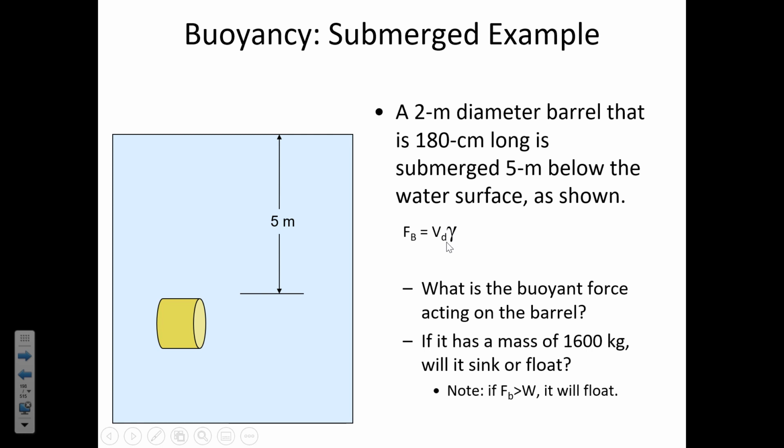You know, liquids are only minusculely compressible. And you'll only notice a difference in the unit weight of the liquid when you go thousands and thousands of meters down. That's when it's such a big pressure that maybe the fluid's compressed a little bit. But basically, density of a liquid is constant, and so will the unit weight. And the volume isn't going to change, unless it's like collapsing as you go deeper under the ocean. And then the buoyancy would change. But let's say this isn't collapsing.